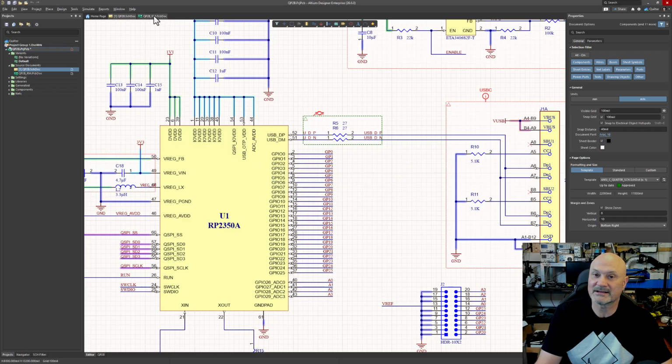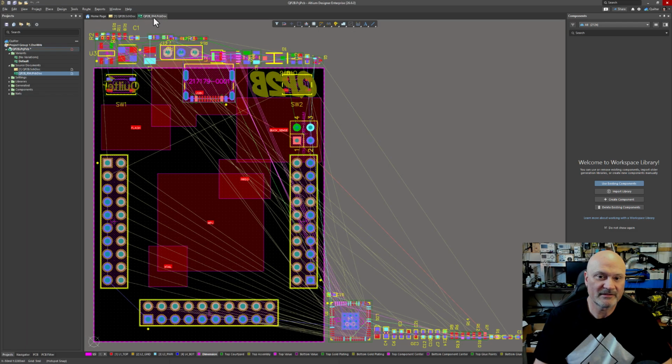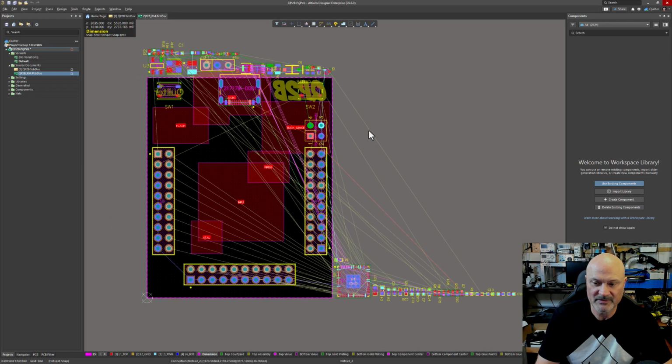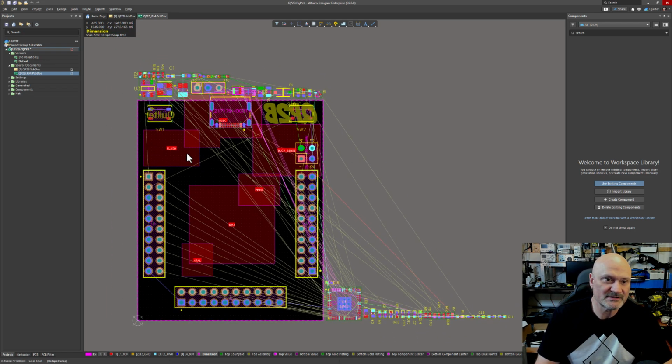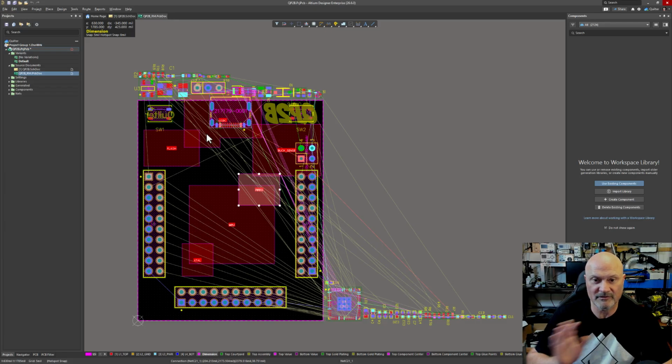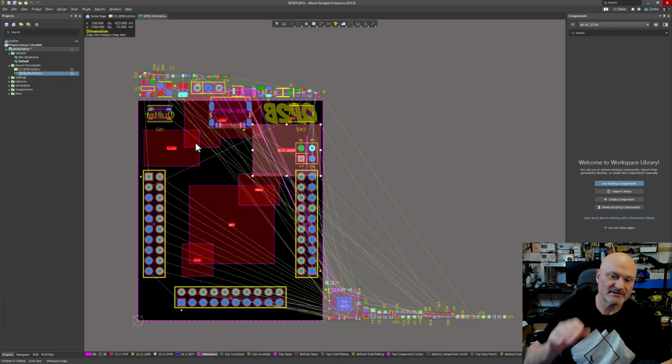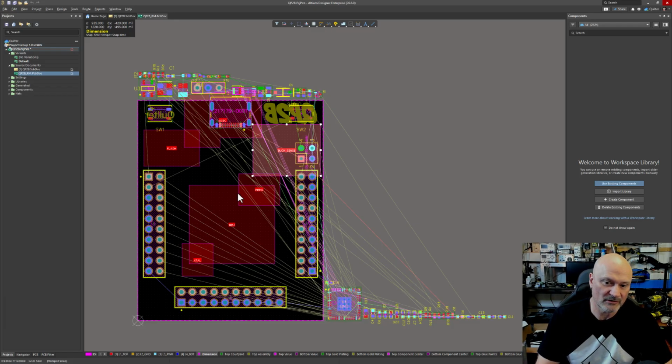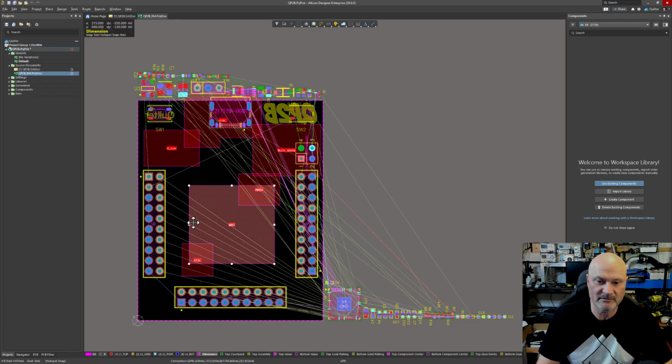And just to give you an idea what I'm starting with, this is the printed circuit board. So here, those blankets came in as rooms in my PCB document, and they can be used in Quilter to pre-plan the floor plan of my board. And I'm defining an area for each of those main circuits. This is a microcontroller board, so I've got the MPU room placed in the middle here.